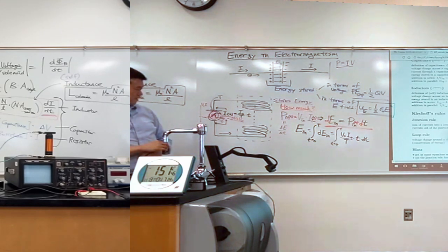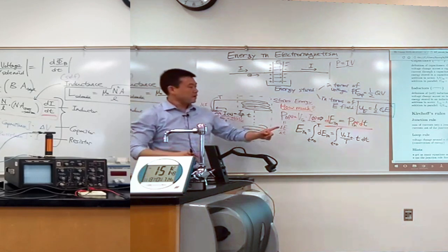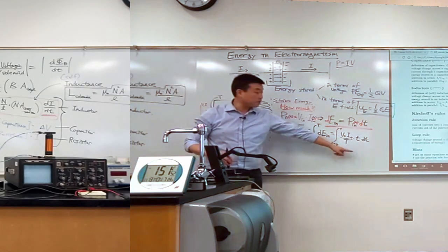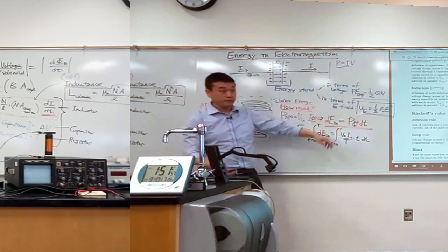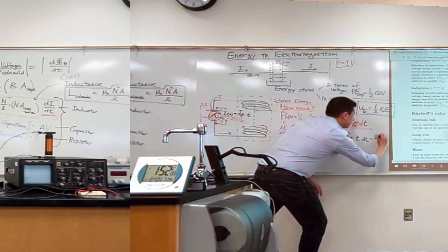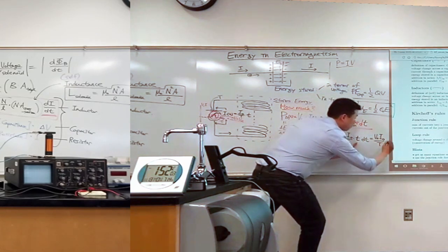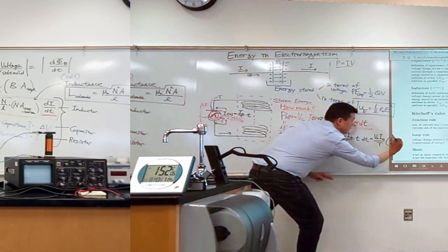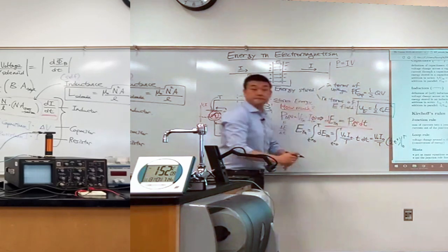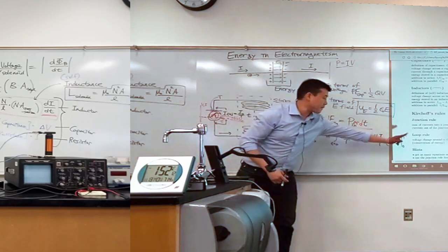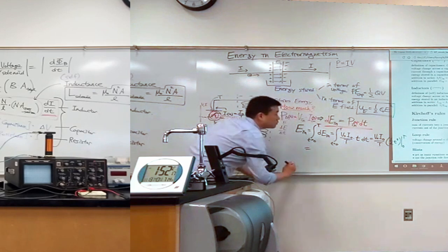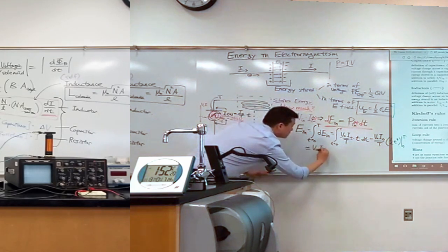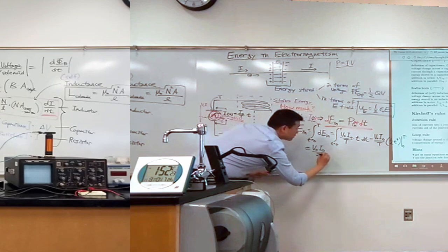All right, are all my units right? Yeah, I think my units are right. So do the integral. It's a simple polynomial integral. The antiderivative is 1/2 t squared. So this is V naught I naught over capital T, 1/2 t squared, evaluated from 0 to capital T. Plug in this capital T. One factor of it cancels, and you get energy in is equal to V naught I naught over 2 times the duration of time T.